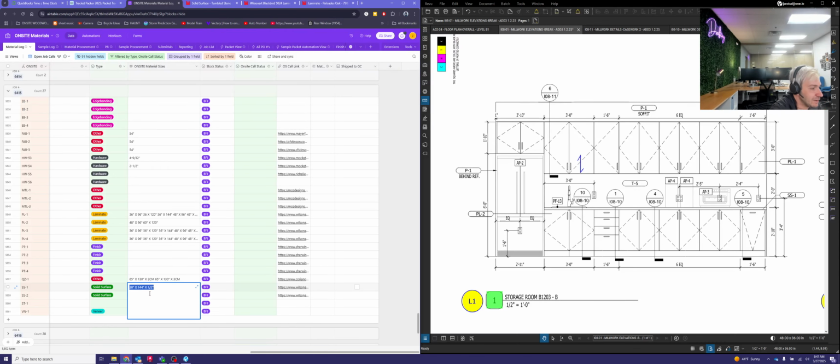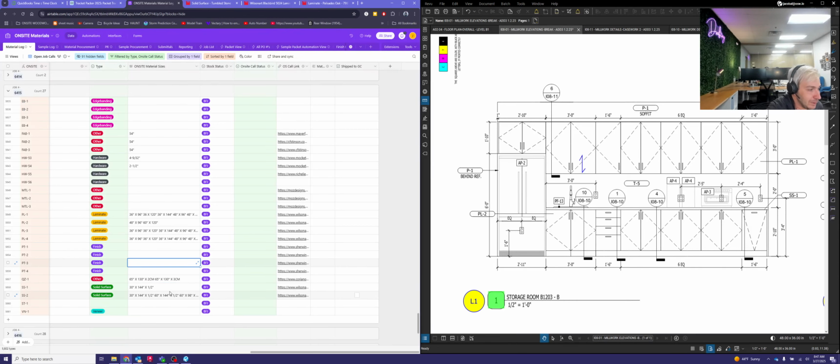You can see that these sheets come in 30 inches by 144 inches, and they are 1/2 inch thick. So when we go to draw that, we have to remember that 1/2 inch thick is really important. That applies to stone, solid surface, quartz, and all the types of countertops like that. You have to pay attention to the thickness of the material because it will affect the way that you draw the countertop in the drawing later. So we do know that it's 1/2 inch thick. That's perfect. That's all we need to know. That is all the finishes that we're going to be dealing with. So we have PL1, PL2, and SS1 here.